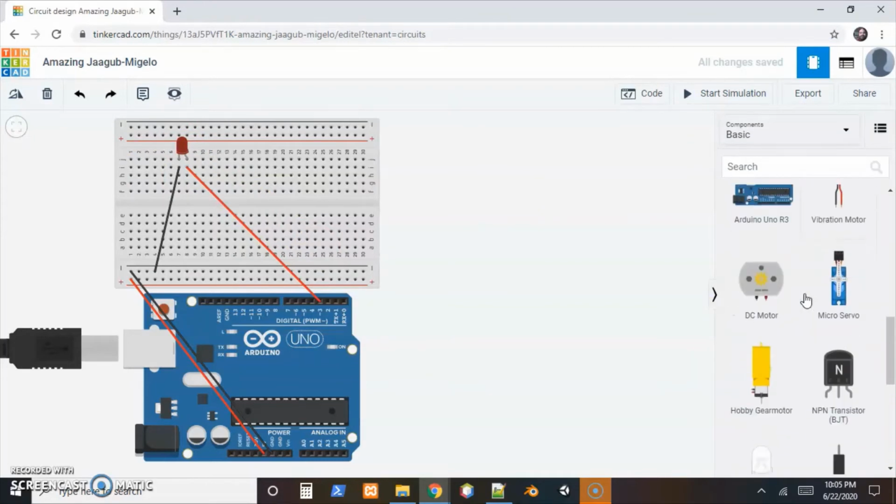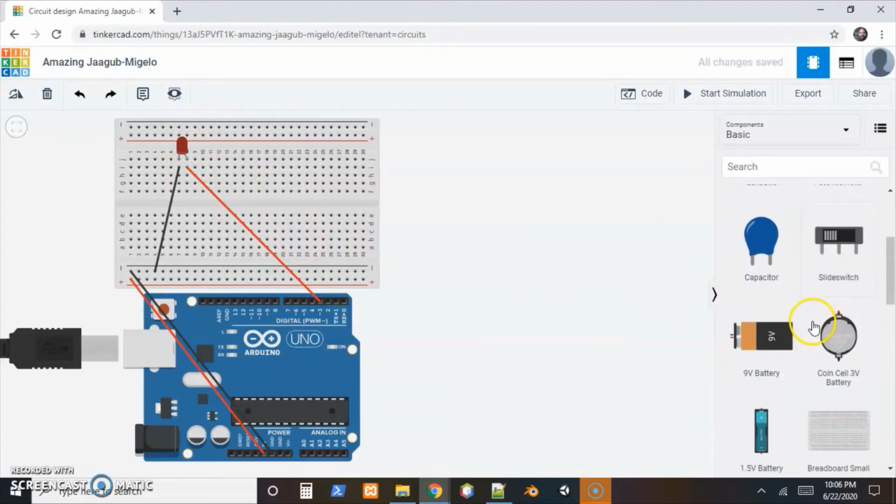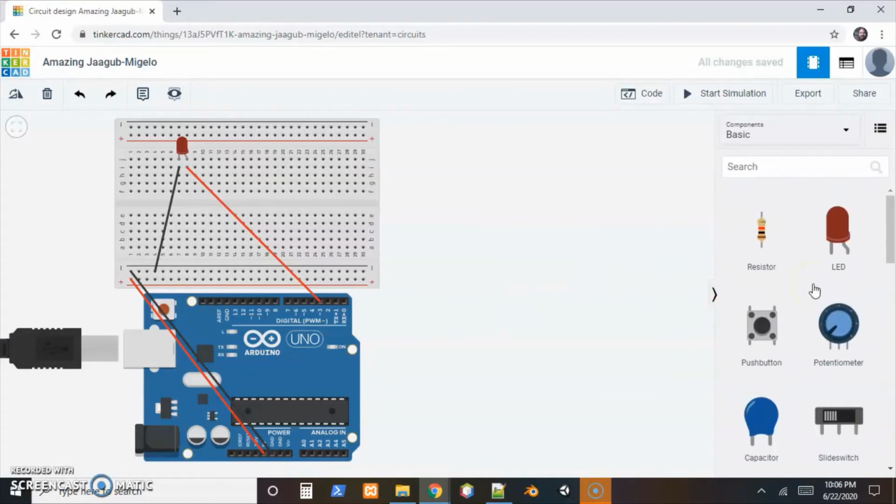But we're introducing this for IoT reasons, and you're probably well aware that while 5 volts will power a small LED, 5 volts isn't going to power the lights in your house. 5 volts isn't going to power your coffee maker if you start setting up some programs for kitchen stuff, a smart kitchen sort of thing. 5 volts will, however, always flip a switch. So for that, you would need the transistors like showed up in the manual. I just want you to be aware of that for scaling things up, but we can skip over it for the lab here.